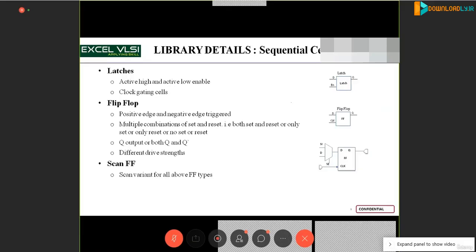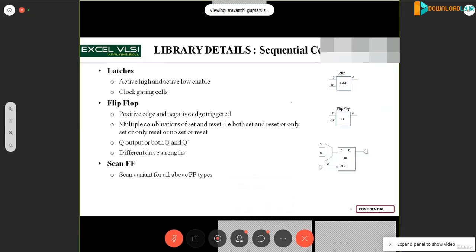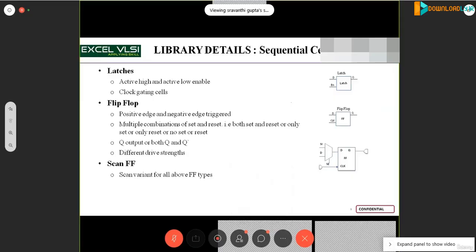There might be some power issues with the RTL, where you need to insert this clock gating cell to optimize the power. In such cases a clock gating cell is inserted in the circuit, and it is switched on and off according to the logic by which you want to propagate the clock. So it is basically turning the propagation of the clock signal on and off.